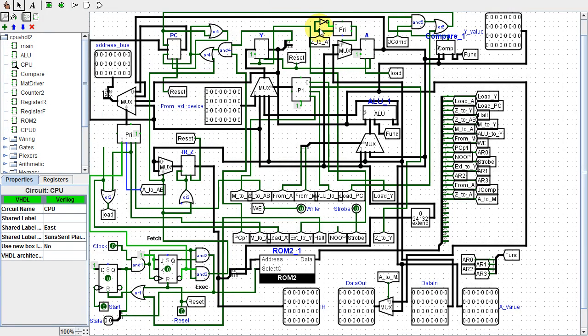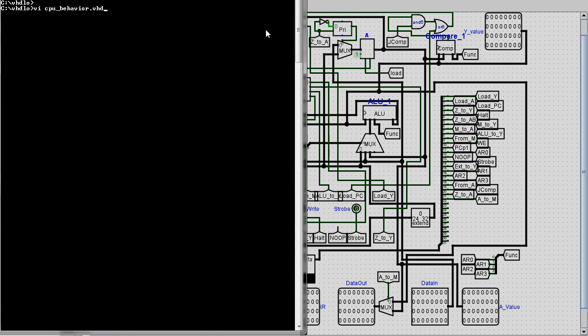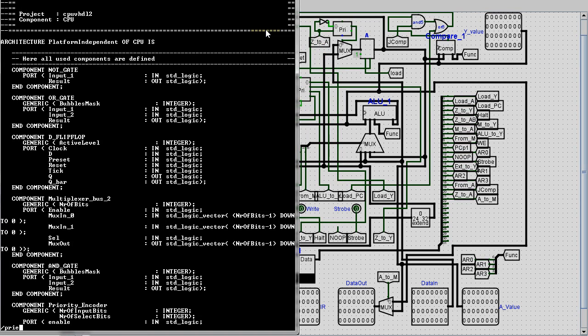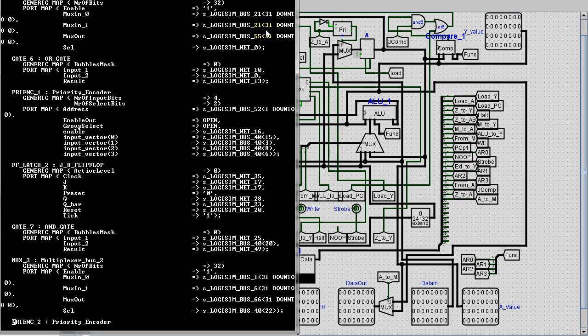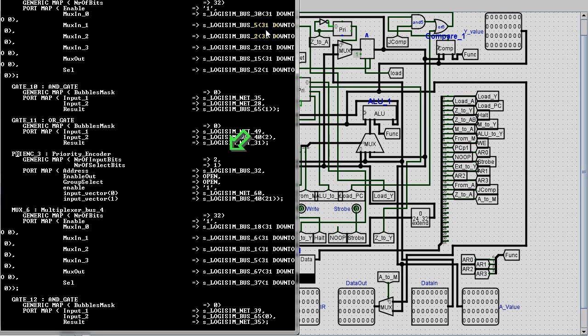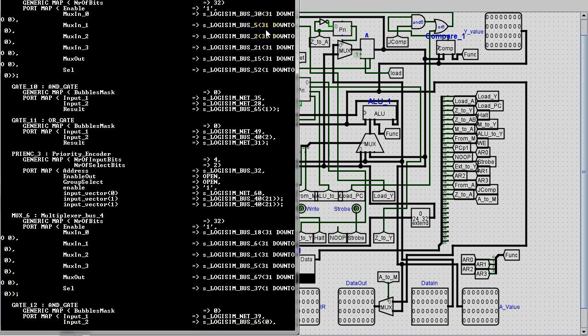The next thing might be a bug with Evolution, but I'm not sure. All of my priority encoders except this one are 4-input encoders. This 2-input encoder doesn't seem to work right. I suspected it is because since the others are 4-input, this one needs to be 4-input as well. So I'll make it a 4-input encoder, making the 2 additional lines 0.